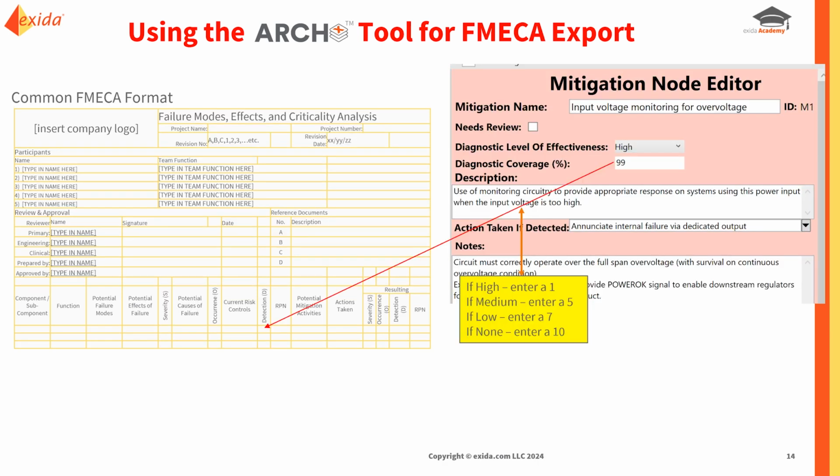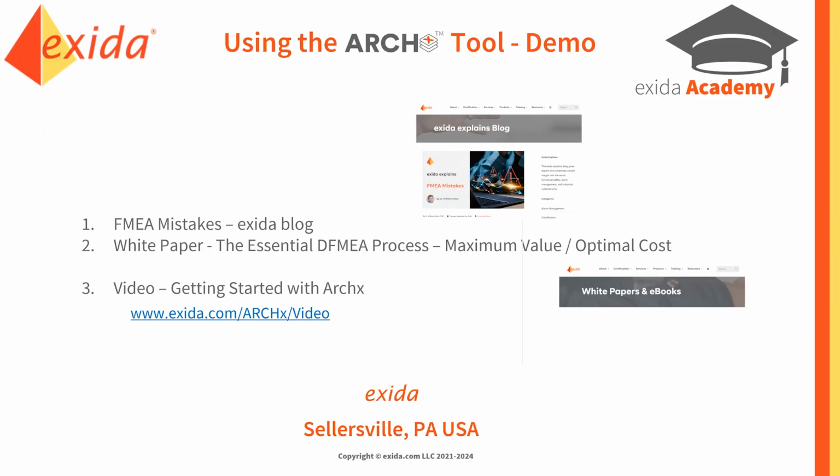And perhaps most importantly, in the functional safety world, we estimate diagnostic coverage factors for each specific automatic diagnostic. And we can enter those numbers for each specific line based on a pull-down menu list or the number entered into the diagnostic coverage.